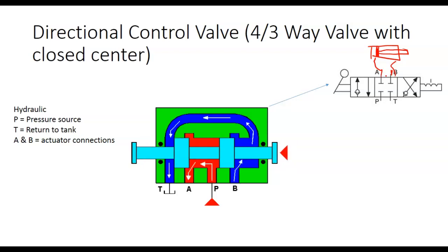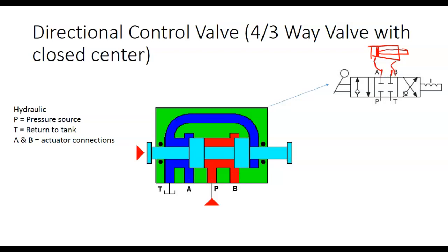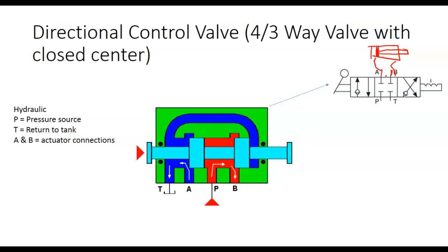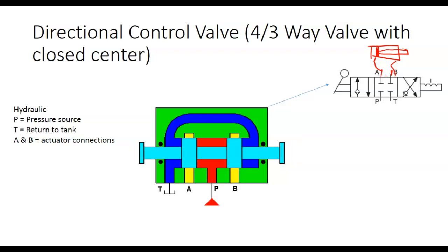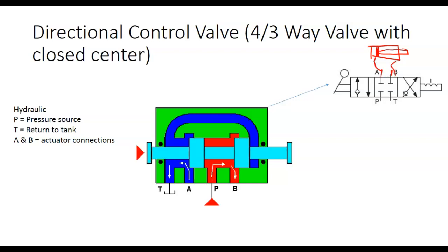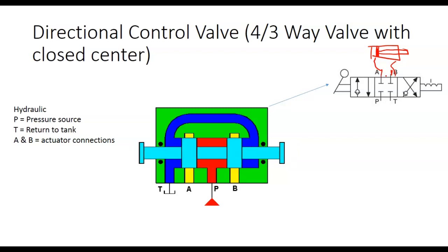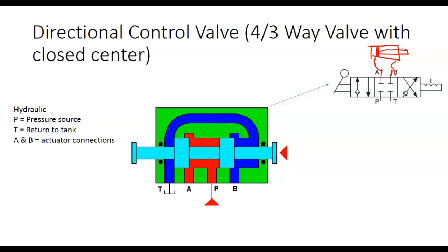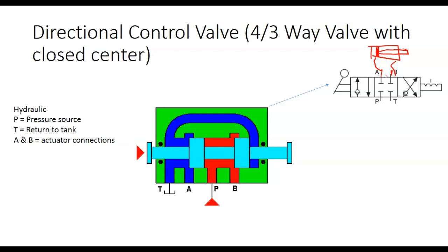So that means if that gripper's open, you can't close it with your hands because there's nowhere for the air to go, right? Y'all understand that? Or if it's closed, you can't open it. You can move it a little bit because it's pneumatics. If it was hydraulics, you couldn't do that. We could stop a hydraulic cylinder anywhere using this closed center, and you could not move that piston. It would not move.